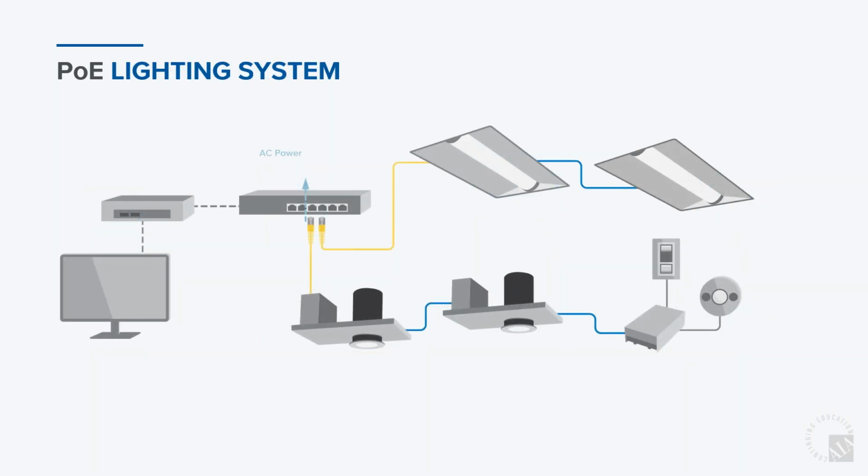So this gives you an example of what a PoE lighting system is. PoE solutions for smart building control all the stuff we just talked about. Its user interface easily creates action sets, scheduling and policies. Gateway, host computer for lighting system. PoE switches route data between the lighting system software and fixtures. Buttons and sensors. Accessory nodes provide connectivity for wall buttons, room sensors, and non-PoE lighting.